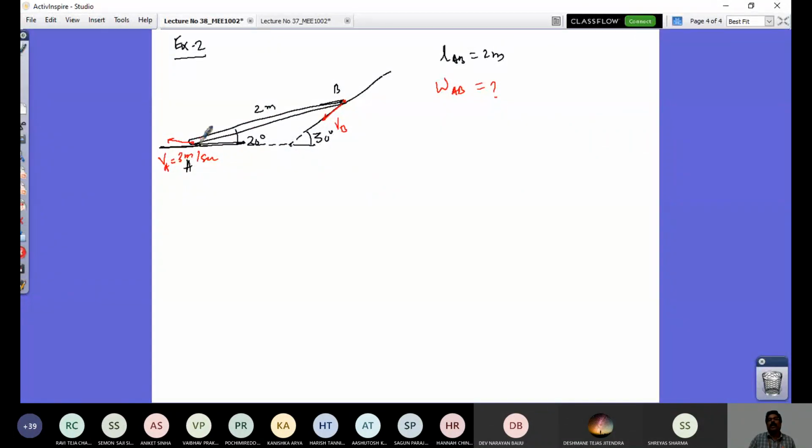See, what would happen if I do not have any resistance here? It's a smooth surface contact. So at the next instant, this 20 degrees is going to reduce further. It becomes 19 degrees, 18 degrees, 17 degrees, and at one point in time this is going to be 0, and the entire AB is on the floor. Point B would come onto this, and that is where it will stop. Maybe it will take some time and then stop, or it comes very slowly. As point B translates here, A translates to the left, B translates along this, there is an instant when this 20 degrees becomes 0, and then all are translating with a common velocity.